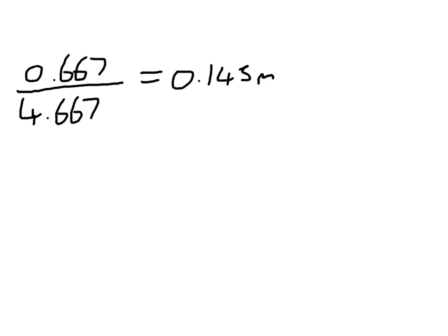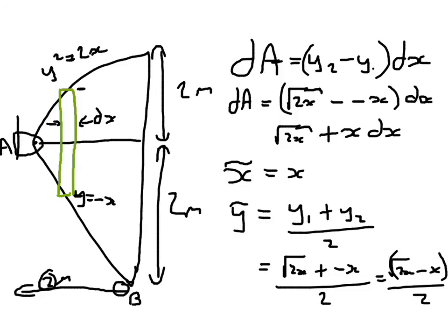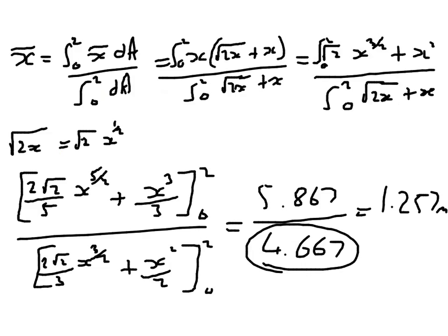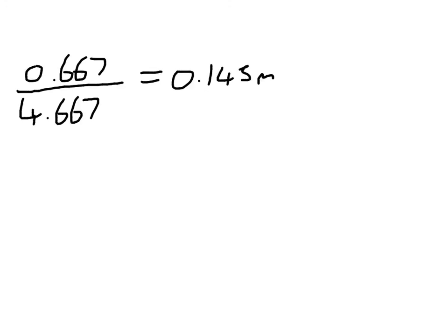So all the way back in our original question, we now know where our force sits. So we now know we have a weight acting here, and we know our x direction is 1.26 metres, and we know our y direction, which I haven't drawn very big, but is 0.143 metres upwards. So now what we need to do is calculate our support reactions.